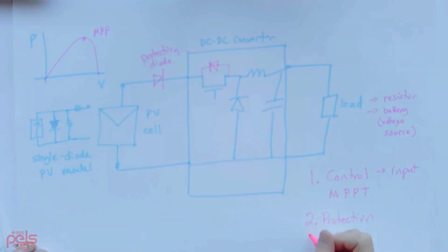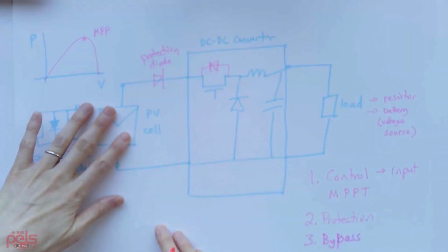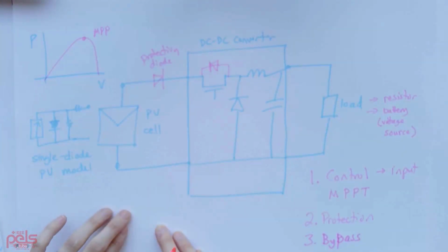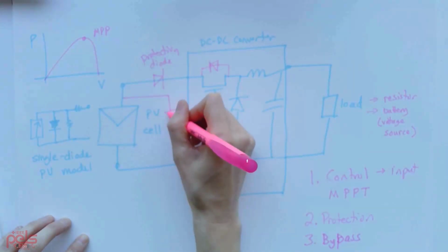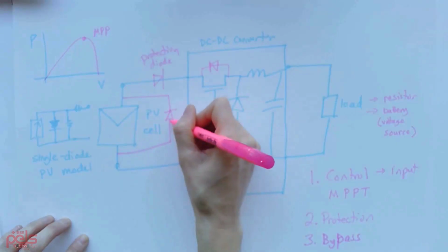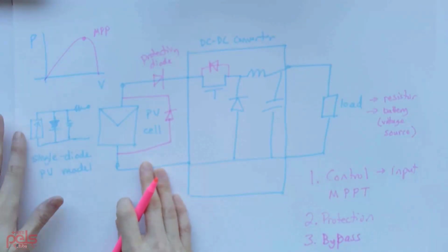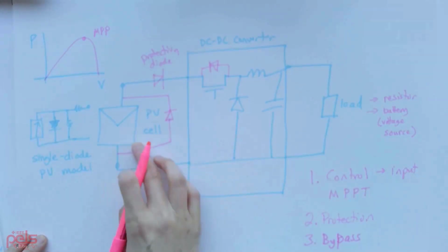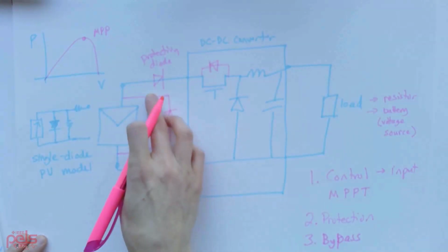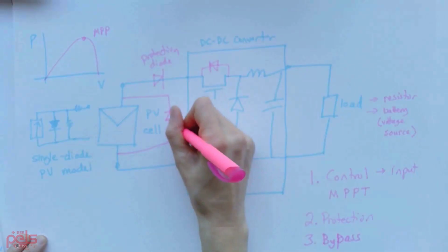The other thing to mention is a bypass. So if we have multiple cells in series, we can bypass each of them, and the bypass diode would be going around in this direction. That's when we want to completely bypass this diode because the current is either too low or insufficient. So that would provide a path for the current to flow around the cell. So this would be a bypass.